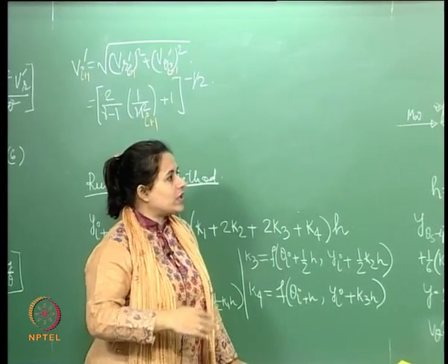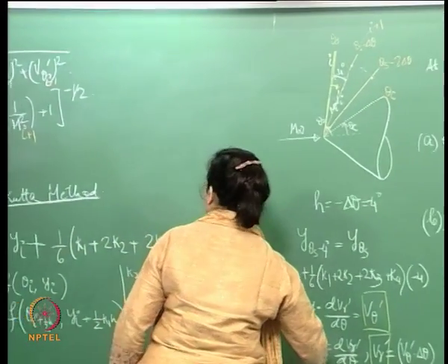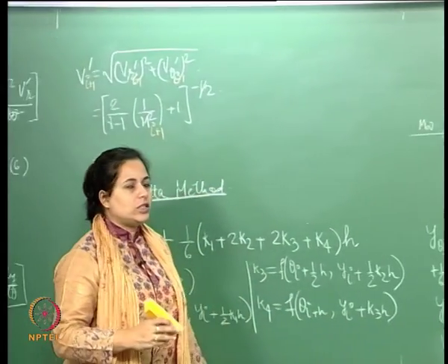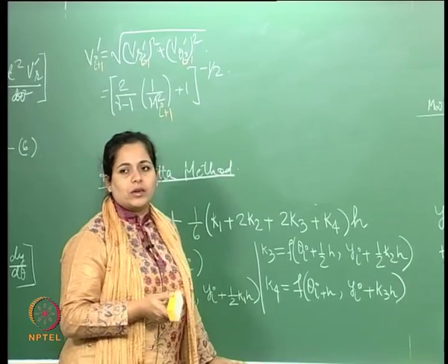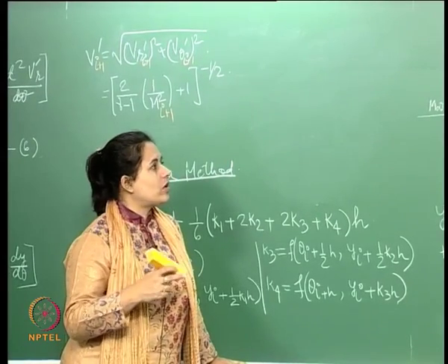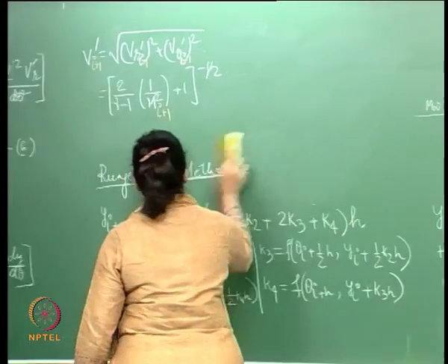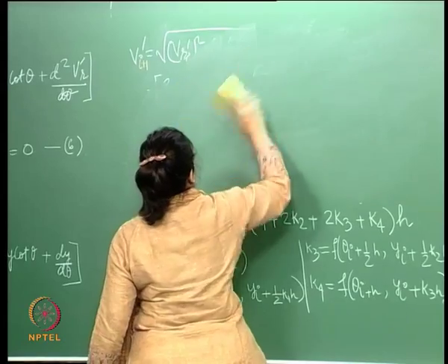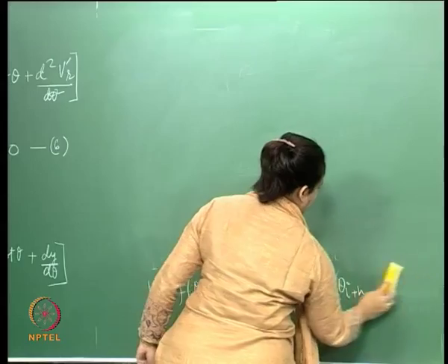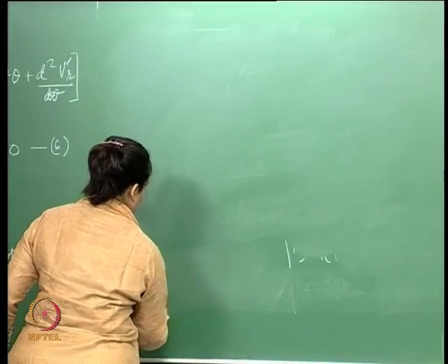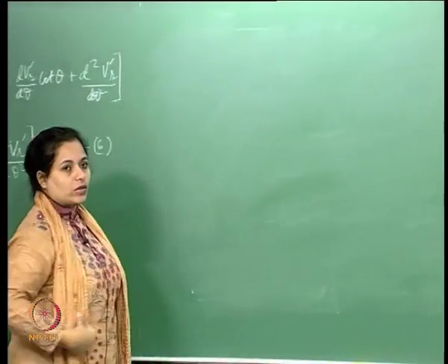So, how would that look for a cone? Essentially, for a cone the shock is weaker for the same theta c and for the same Mach number. For a 3D cone the shock is weaker than that of a wedge. You should be able to get properties from your numerical values, and then cross check.